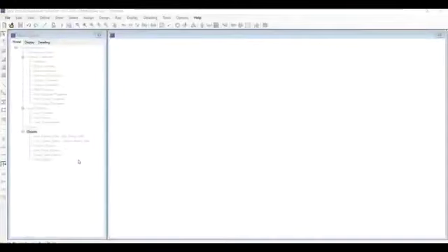Hi guys, now we are going to design a footing called the mat footing. For a mat foundation design, firstly we need to have the resultant values from our previously designed building, from any software like ETABS, SAP, or STAAD Pro. We need to have the axial forces of the columns at the base level, or the shear forces of the columns at the base level. We need to have all these base reaction values so that we can assign those load values to the mat footing.